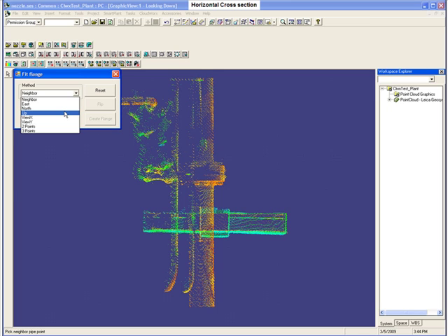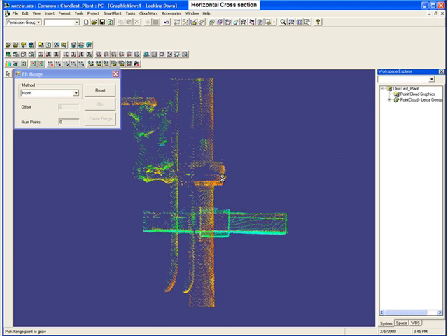It depends on the coordinate system that you're set in. Okay, I know that this is set to where north is up here. Once you've got your directions set, you need to make your first pick. Your first pick is going to be in the center area of the flange. So you pick here, and it's going to create a temporary flange. You want to make sure that's correct. If it's not correct, press reset, and then just click here again.